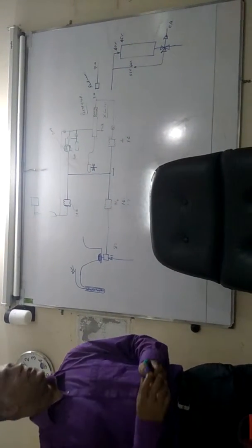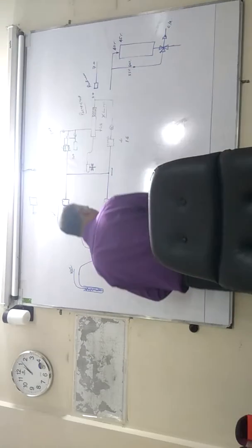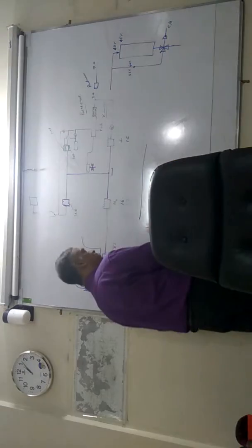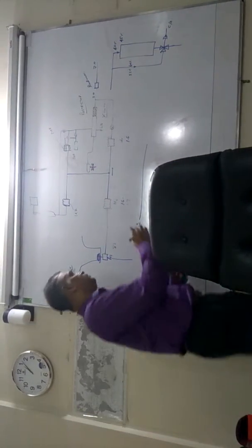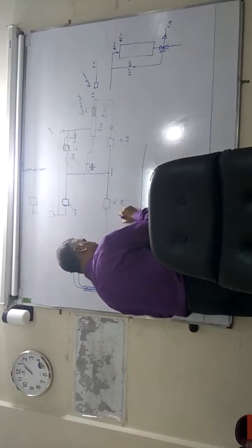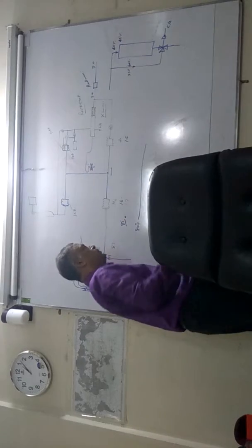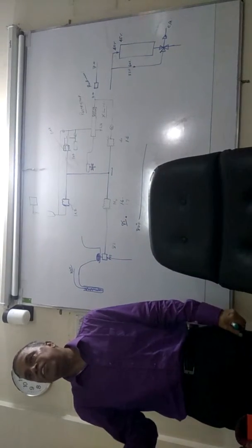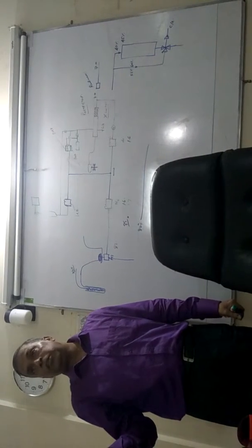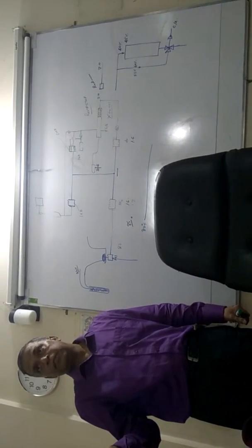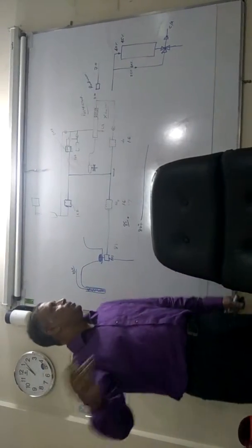Yes? So then what happens, let us just try it. Our required temperature is 80 degrees C, right? And the temperature rises a little more, say now 85 degree C, and the valve is giving full deflection. Yes? Closed. Nozzle is closed. So what happens?